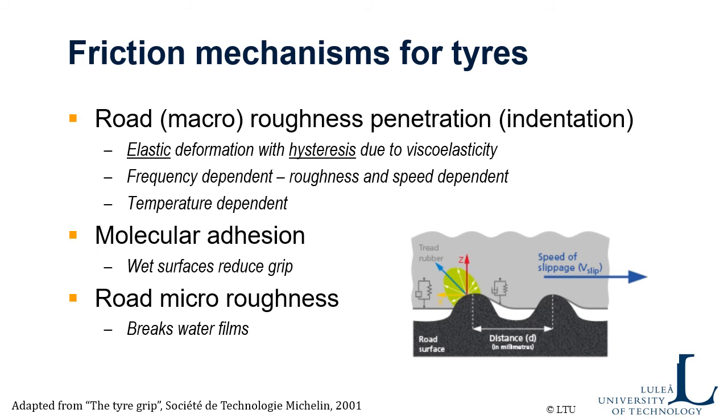So the same wheel, the same rubber, the same tire is not as good at +30 as at -30. It depends very much on the type of rubber you're using in the tire. So winter tires made for Nordic climate, minus 10 or so, are made of a softer rubber than the summer tires.